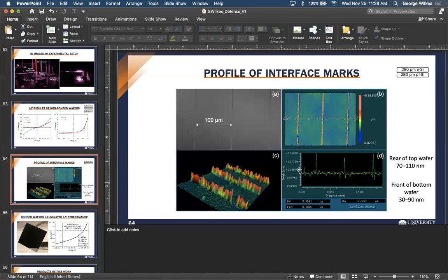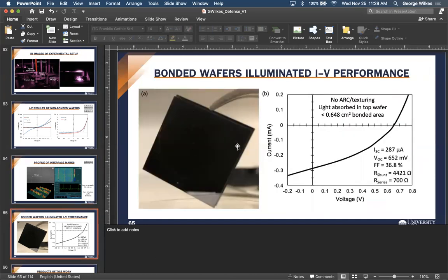Yeah. Nice. So when people do that type of direct bonding, they usually activate the surface using plasma treatment. Have you ever tried that pre-treatment in your case, or is it just a bare wafer that you bond? I cleaned the wafers with HF. I did actually, for this device, I forgot to mention, I used aluminum oxide to passivate these for the photovoltaic device, and I did an anneal on those to improve their passivation. At the interface, have you ever done the plasma treatment before bonding, or do you just bond without any? Okay, I see. No plasma treatment. I think that might help. That is the useful, conventional way. So yeah, I think this is very interesting work. I'm very impressed by those things.